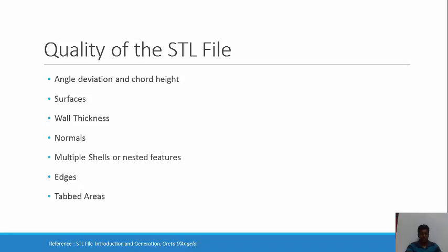Next comes edges. Especially in Rhino, when trimming an object or whenever you create a new one, some edges can be left behind in the model. Be sure that we avoid them. They can create confusion during the processing of the file.